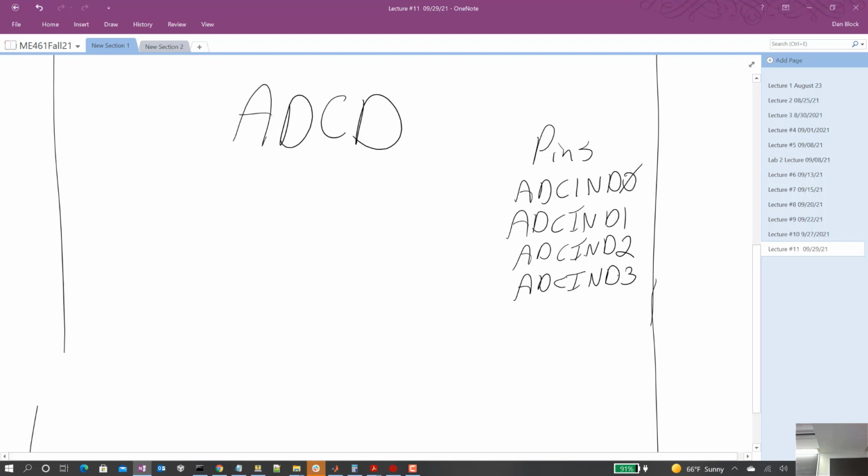Anyway, we have this, but we actually have more. We have ADC in D4, D5. Those I do not believe, yes they do. They come out actually on this red board. Yeah, you can't really see it. You can put some really nice high fidelity BNC connectors on here, and it goes through a transceiver chip and all this kind of fun stuff. That again would use the differential capabilities of the ADCD. But again, we're not going to use those. Actually, we're only going to use in lab ADC D0 and D1, but you could sample all 4 of those, or you could sample all 6 of the in pins for D.